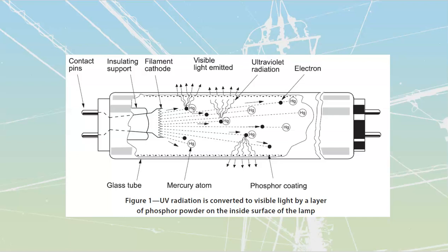We've got a couple of main components. I'm going to highlight the main components, then we're going to talk about the interaction. The first main component is this setup over here. We are going to call that our cathode. We have a cathode at either end of every fluorescent tube, not because we have two negative points, but because we have two points that act as the negatives inside of our circuit.